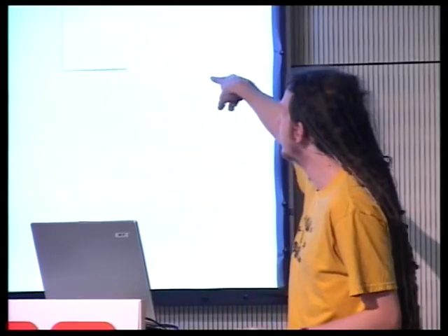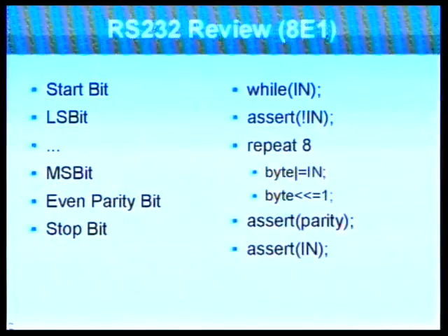To send 0x90, again, we have the less significant bits, followed by the 1. And then we have the most significant bit. That's the 8th bit in the 9 nibble. But here the parity bit is 0. If you look at these enough, it's easy to recognize the difference in a scope recording.